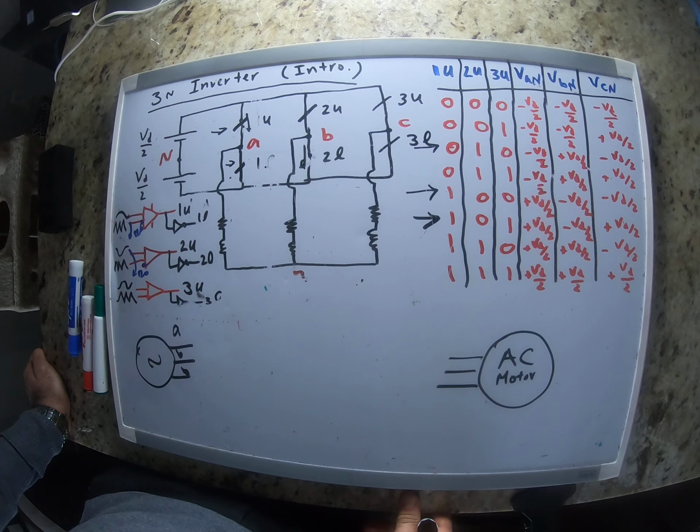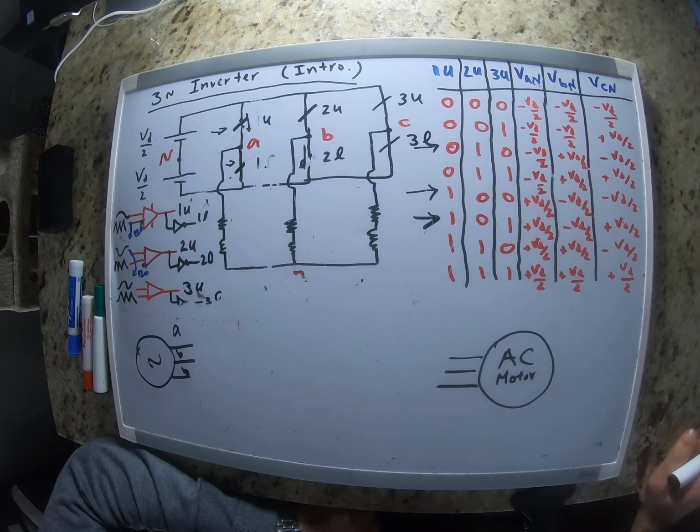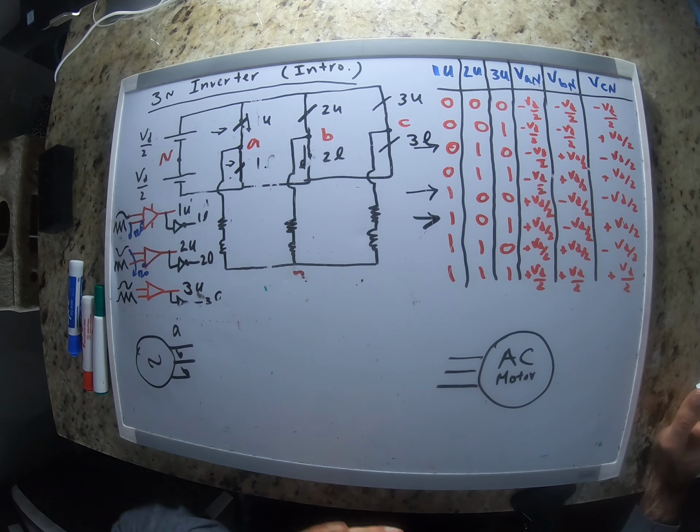motor. Now, controlling AC motors like an induction motor or synchronous motor is not as simple as controlling DC motors, because if you remember, when we discussed choppers, we saw that, for example, with a 4-quadrant chopper, we can control the speed of a DC motor very easily. We can increase the voltage, and by increasing the voltage, we would have higher speed, and we can reverse the polarity of the voltage and current. So you can just have the motor rotating in the opposite direction if you want.